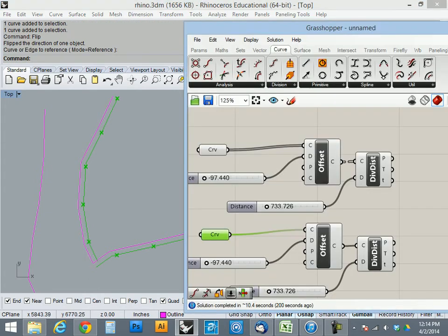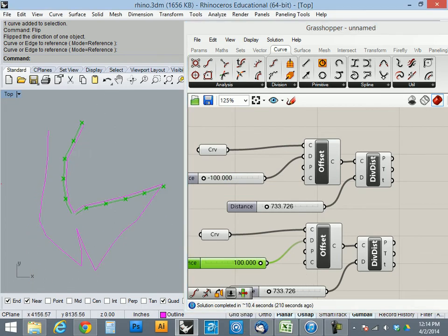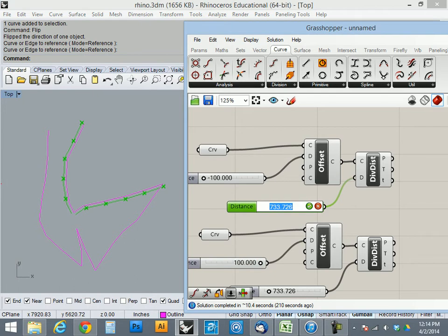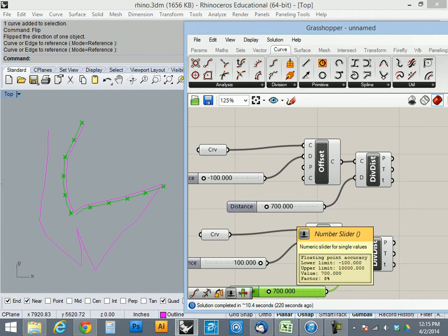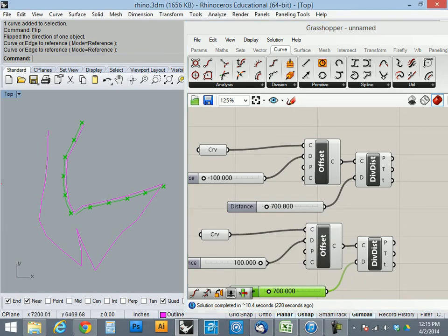So we'll set one curve there. Let's set one curve here. Let's make our offset negative 100, and we'll make this positive 100. So these holes now should line up. And if this distance was, let's say we're working in millimeters, so now the spacing of these should be identically in the right position. Like that is there. We're getting an extra one here just because of the way the offset is.